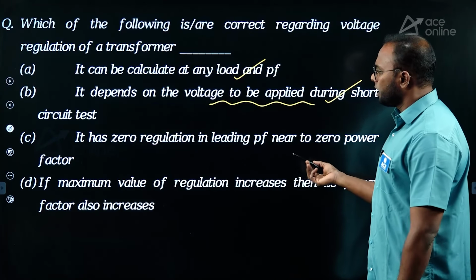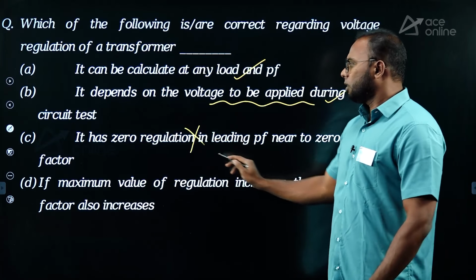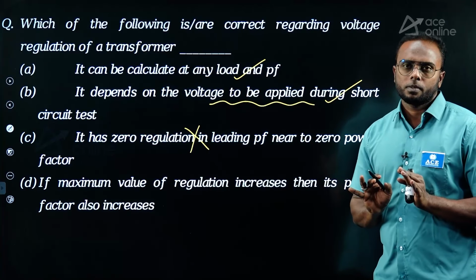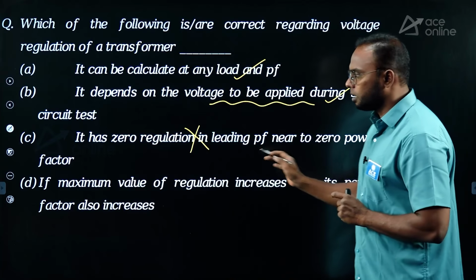Third, it has zero regulation in leading power factor near to zero. This is wrong. Zero regulation in leading is okay, but where we get zero regulation, it is always near to unity power factor, not zero.